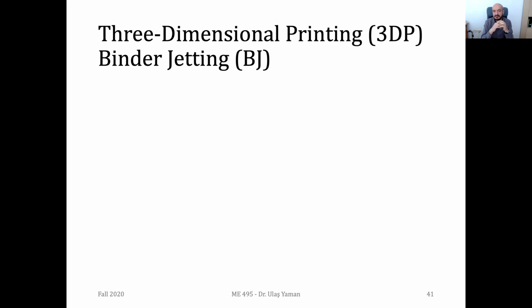Since we cannot have internal structures in material jetting or binder jetting, we need to fill the slices completely by having various scanning patterns, but the rest is the same as, let's say, SLS or SLA. Colors and different types of materials need to be specified in the CAM software, right? Yes, if you have different colors or materials, and if your printer is capable of that, you need to do it in the CAM software. Okay, thank you. You're welcome.